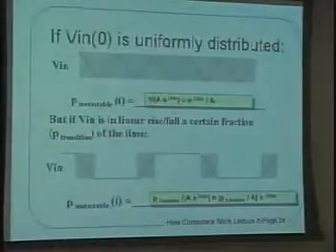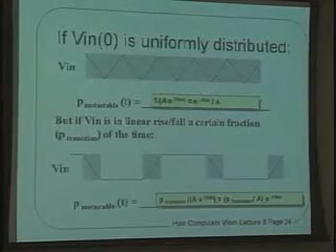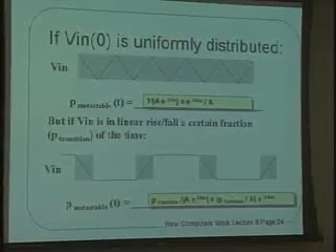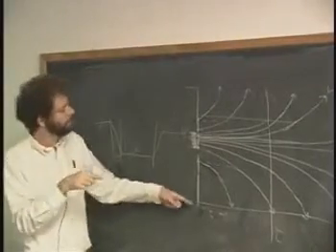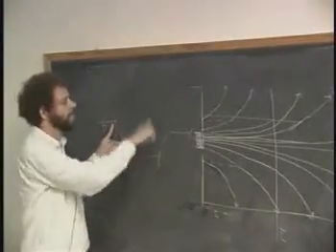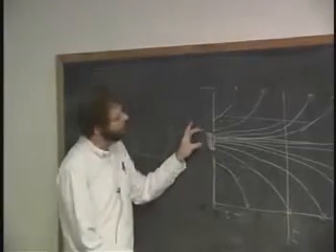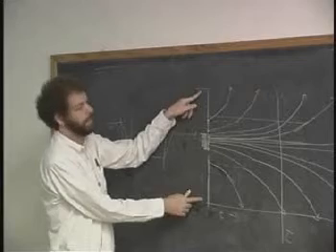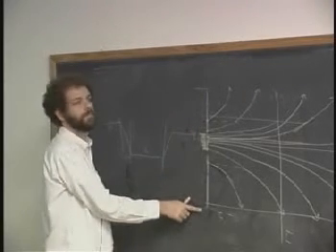And from that, I can get the question that you asked, which is what is the probability that I will be metastable past a certain time? Well, if the voltage was going up and down and up and down, the nerd was sitting there pushing the Coke button over and over and over again, so that this voltage was always in transition, then the probability that it's going to take more than this time is this length divided by that length, because it's equally likely to be in any of the places here on the y-axis.